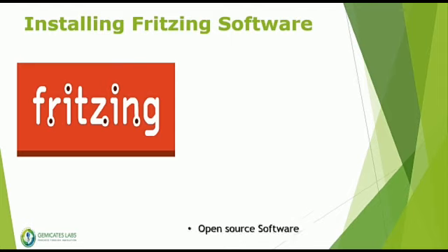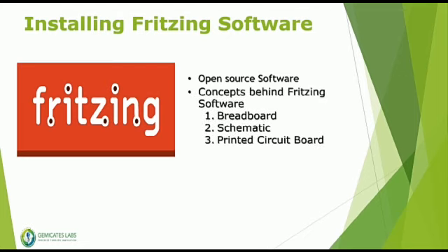Fritzing software is an open source software where anyone can design their prototype. To understand Fritzing, it is important to know the concepts behind it. The concepts are breadboard view. Fritzing can present a circuit in breadboard view and makes it easy to visualize how components will fit together and be wired together. The next concept is schematic view.